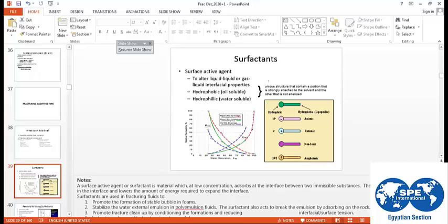How are we selecting the gelling agent concentration? We have our reservoir temperature, and we are designing the frac fluid to have the minimum viscosity to carry the proppant according to the proppant selection. So you are doing a test in the lab. We have a chart with the viscosity of the linear gel at room temperature, which should equal a certain value to have the required viscosity inside the reservoir against the reservoir temperature.